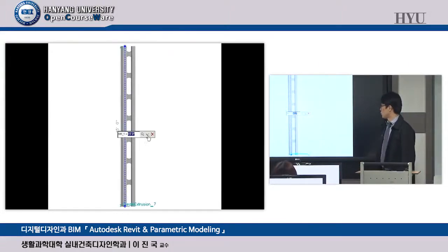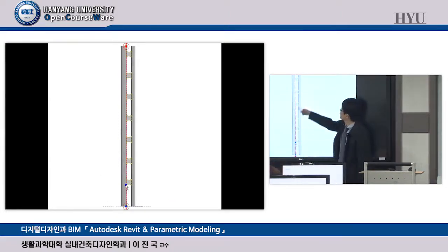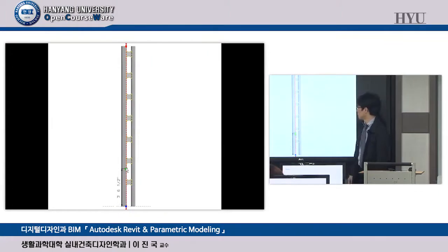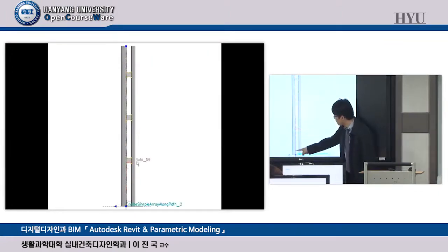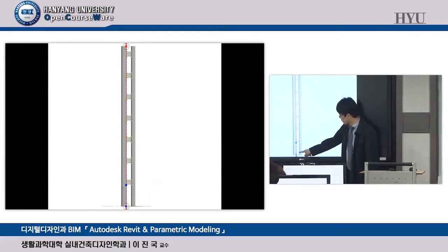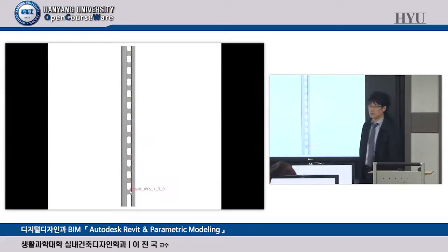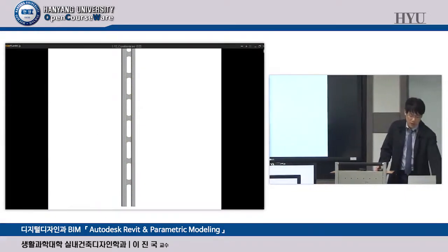And at this time, click the mullion web and it's constrained. Take a look. Basic distance and the last point distance are predetermined. Okay, so if you change the gap, the mullion gaps will change. But this one has some structural problem. So if you change the gap from the starting point to shorter than before, around here, then a lot of webs are going to be installed automatically like this until the end point. Okay, this is the fundamental approach of parametric modeling.